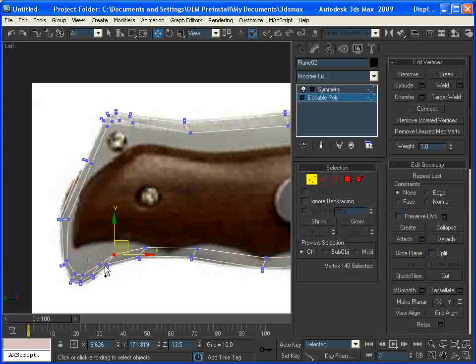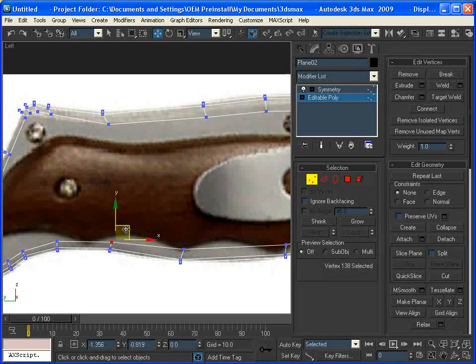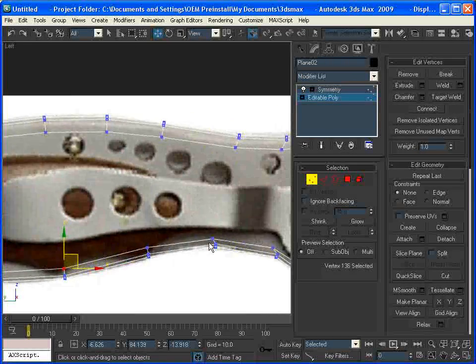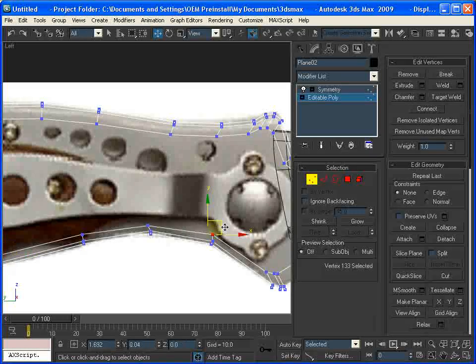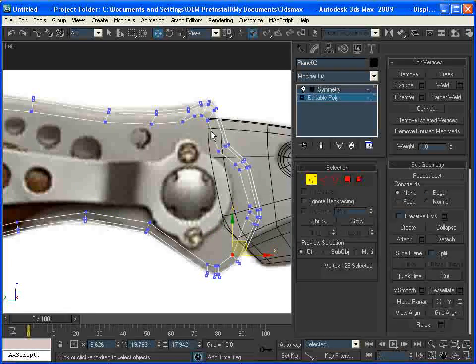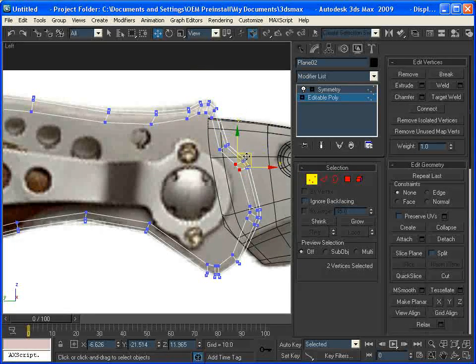And basically what we're doing here is just creating the supporting edge around the edge of the entire thing, but we're doing it by extruding in a border and then using that border as the supporting edge. Then we'll scale it in one more time and then cap it off, and we should be good to go without having to fiddle around too much with quadrifying everything. We'll get the same result but less effort, which is always good when you work by the hour, or when you just want to finish things quickly and be the envy of all your friends and your boss.